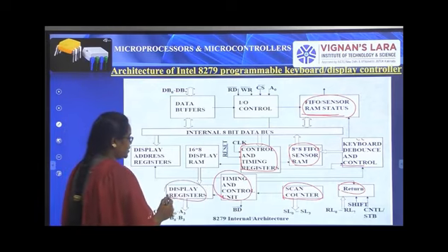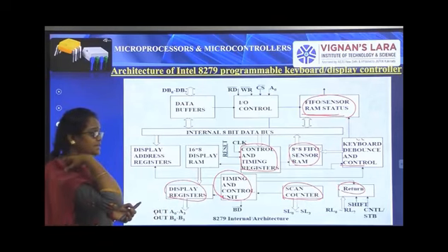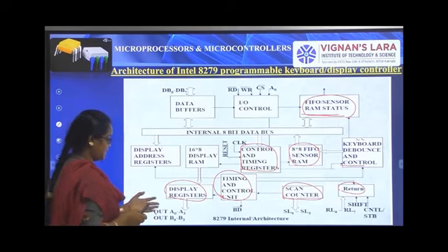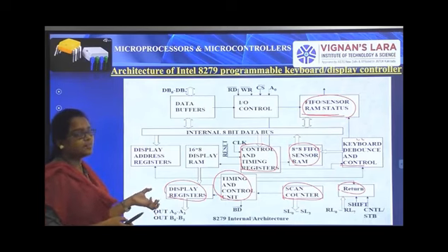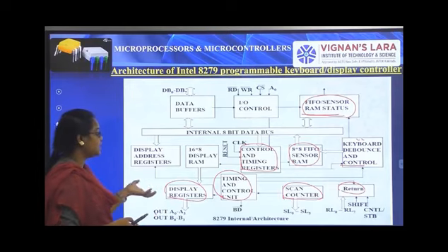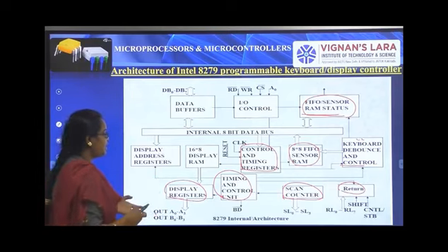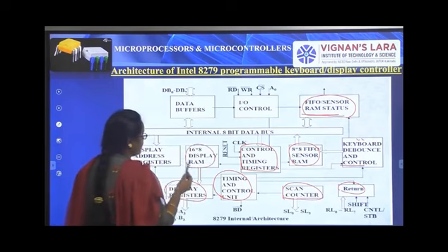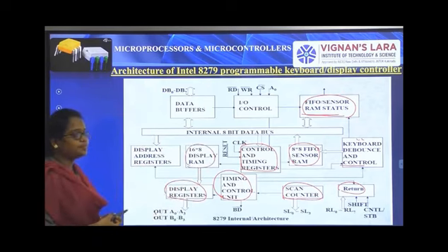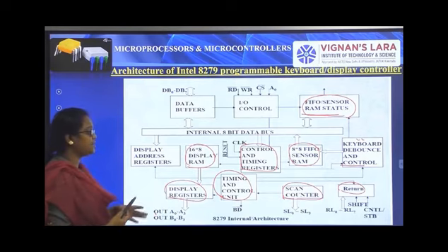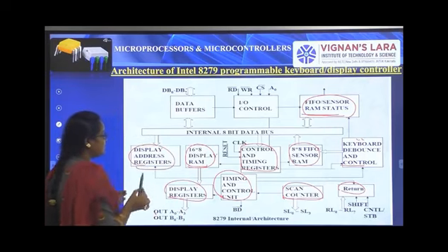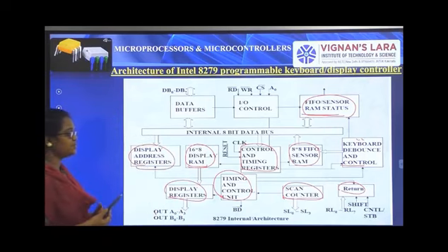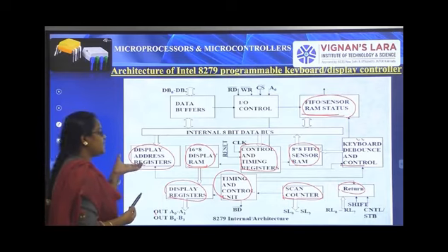Display registers store whatever is pressed on the keyboard and the outputs coming from the 8086 microprocessor. The 16x8 display RAM holds the output displayed by the display unit, and the display address registers store the address of that output.